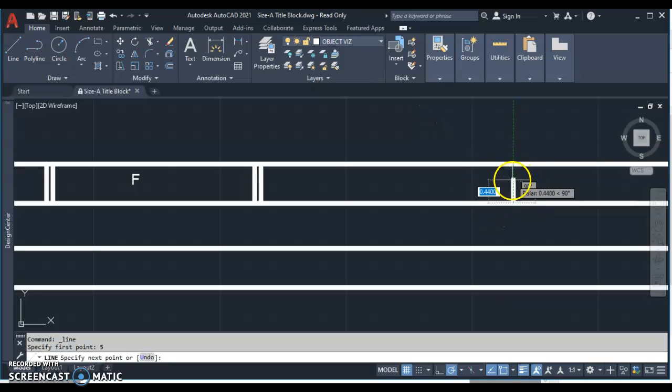Now this part has an angle on it. I could draw up like this and know that that's where I'm going to cut this off. In fact, for our purpose, I'll just do that right now. And I'm going to start a new line at that same endpoint. I could also draw my line on an angle. So here's my angle. You see I have my polar projections, so my angles are locking at 45, 90, 135, 180. We can keep going around. So here's a back angle at 45. Okay, and hit escape, and I got my part in there.